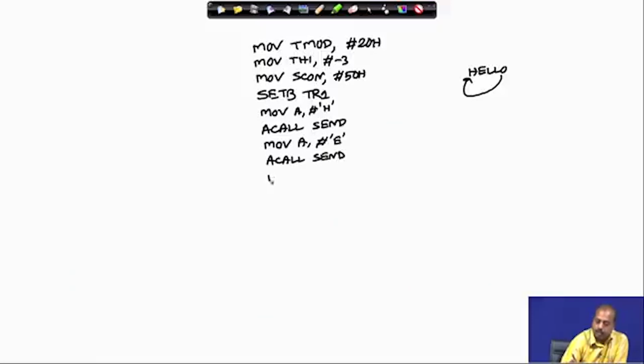Then H E, then L: MOV A, #'L', and another CALL send. H E L, another L. So, MOV A, #'L', CALL send.